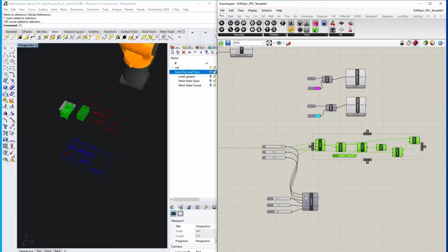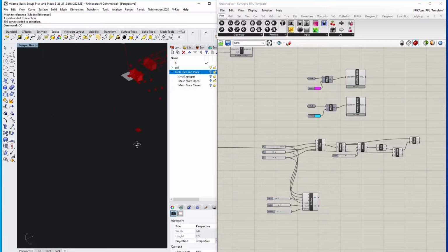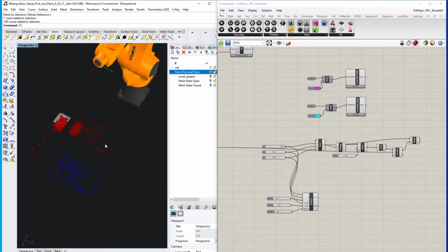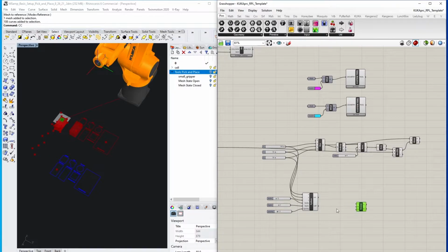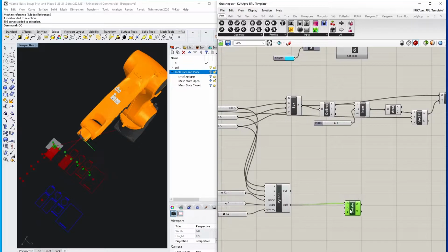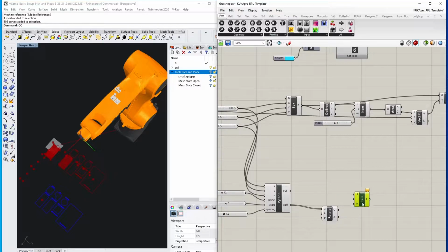So right now we have a series of points that are mapped in the formation of a brick wall, but they are not mapped to our placement area and they are oriented the wrong way. So the first thing we can do is actually rotate this geometry. We can take in this wall. Well, since it rotated it for us automatically, we can now use a list item command in order to move it to the correct location.